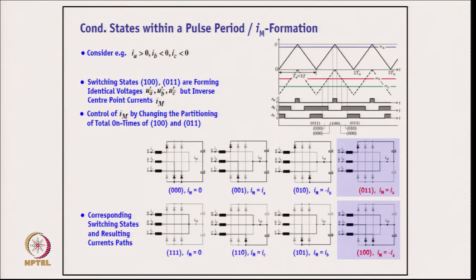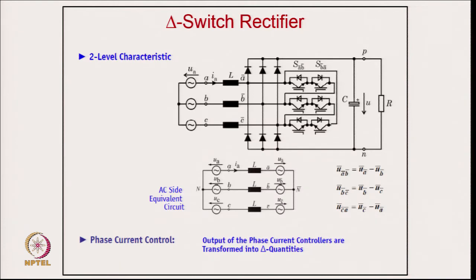Of course, these are the different modes of operation. Here you can have typically 8 modes of operation of these converters for the purpose of switching, to get boost operation as well as maintain the power quality on the supply side. And this is another version of this, which we call the delta switch converter, for unidirectional power flow, where the switches are connected in delta manner, not in star with the midpoint. The benefit is that you do not need the 2 capacitors here on the DC side, and it is able to control the output voltage regulation, as well as get sinusoidal current on the input side.